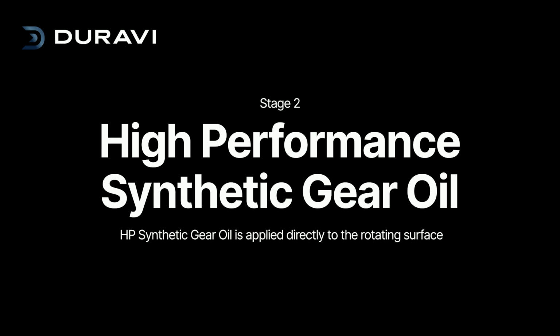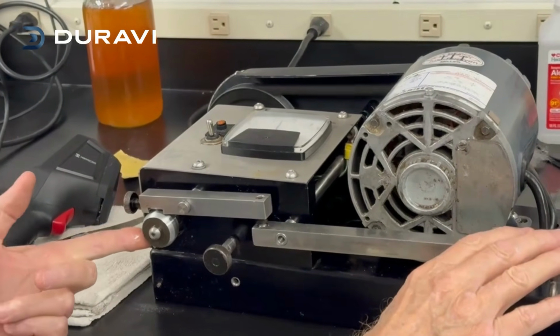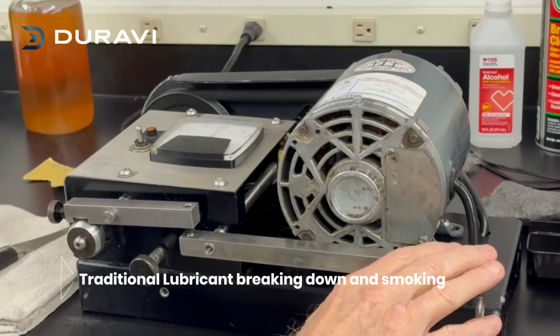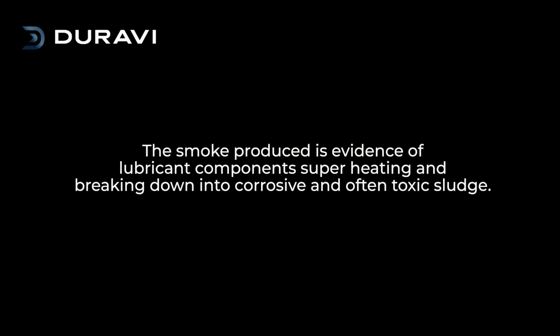Stage 2, high-performance synthetic gear oil. HP synthetic gear oil is applied directly to the rotating surface. No additives inside. So watch. See the heat? The slight reduction in initial stress and the subsequent minor increase in time to weld, TTW, are observable along with the results of petrolubricant breakdown at weld. The smoke produced is evidence of lubricant components superheating and breaking down into corrosive and often toxic sludge.